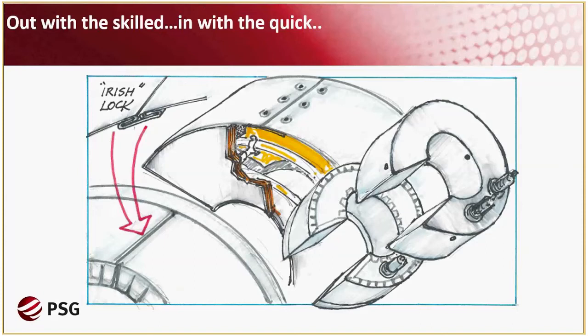You didn't have that retainer that encroached a half or 3/4 of an inch over your channel letter. With channel loom and letterhead, you had it almost trimless. But the profile of the letter, that 5 inches, would show a bell effect on the corners because of an uneven thickness, so that the can itself looked distorted.